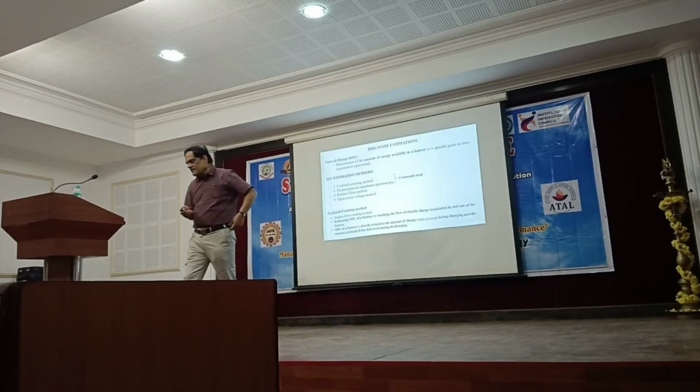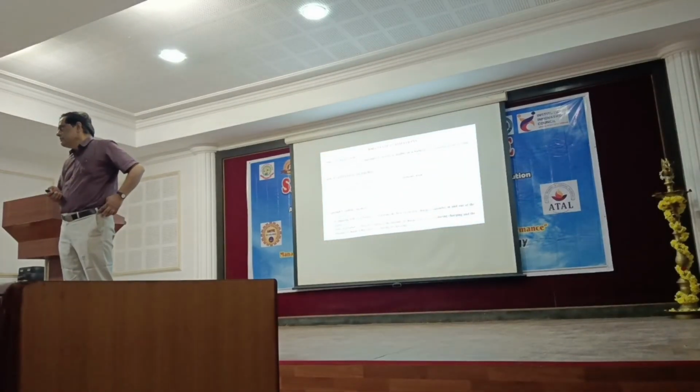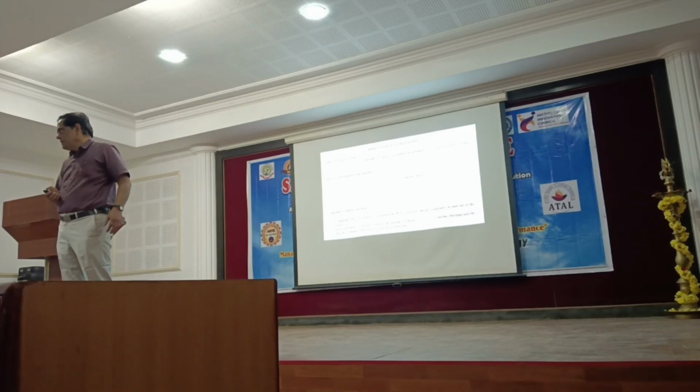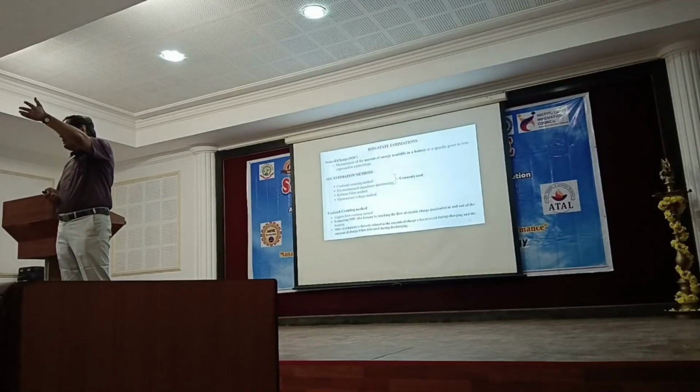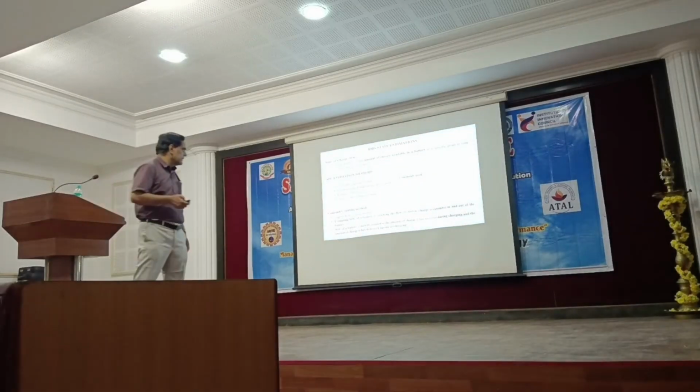In signal processing, what is the role of Kalman filter? What does it do? It removes the noise, removes the error. You will be able to estimate precise SOC for the given battery pack. You are measuring the signal continuously, you remove the noise, like filtering. You will be able to estimate SOC more accurately based on the Kalman filter technique.